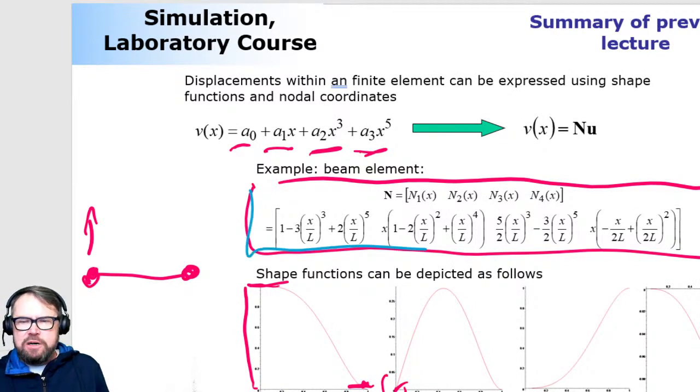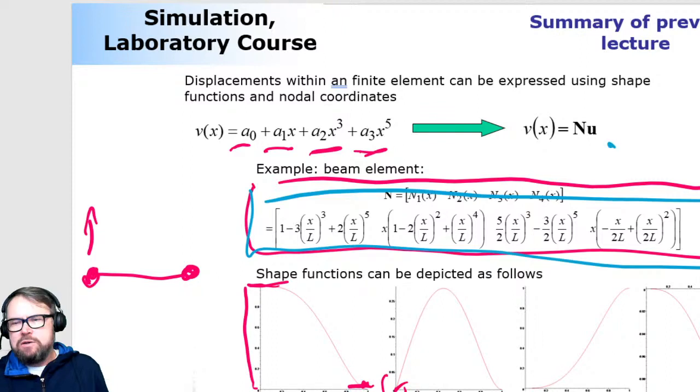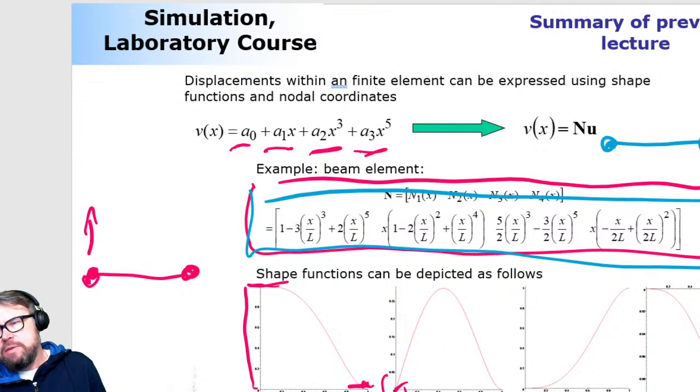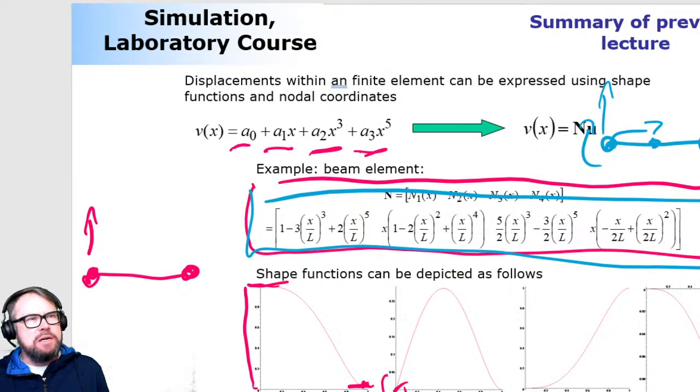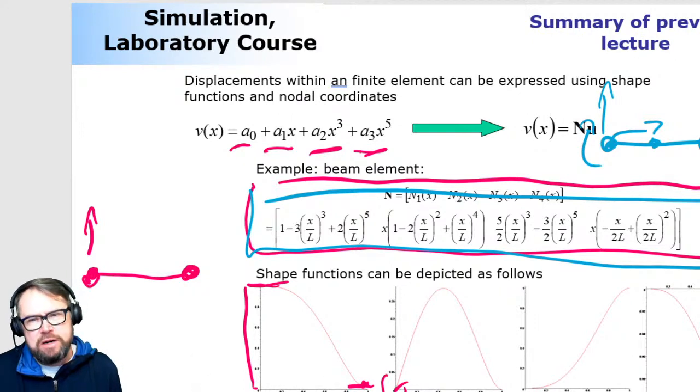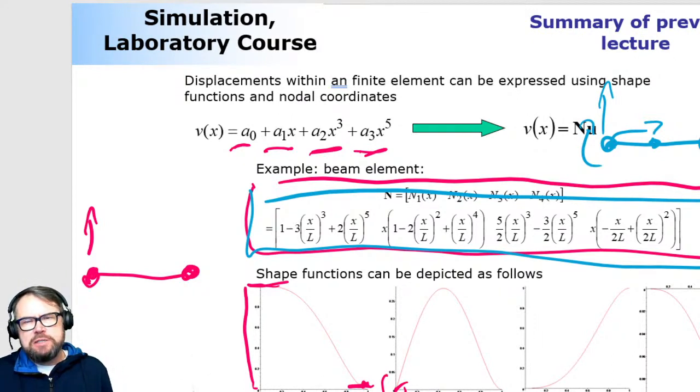These shape functions are describing a beam element which consists of 2 nodes, and each one of the nodes has 2 degrees of freedom. These 2 degrees of freedom are movement in a transverse direction and rotation, like this. I could also have an axial direction here. That's going to be okay. I could have a node in the middle. All that is possible, but I just selected that as one option. To answer the question, no particular reason.